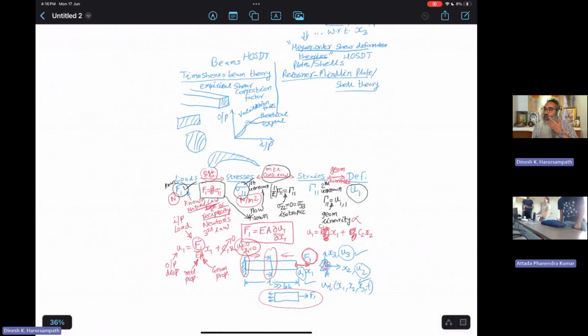Thank you so much. It's a real pleasure. One of the things I'll talk about in a little more detail on Wednesday when you're present is that I also want you to reason out why you're putting something somewhere. Some of them might be quite obvious to put in a particular location, but there are certain variables which are compound variables. For example, today we dealt with bending stiffness, EI. EI has both a material property, E, as well as a geometric property, I. If you're putting E and I separately, then you know where to put them. But if you're putting EI as a bending stiffness, then it appears under both material and geometry. So there are some things which might repeat.